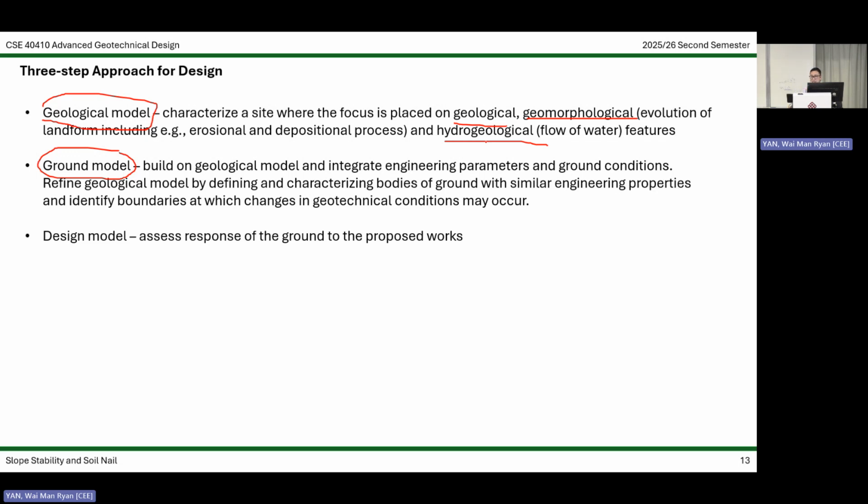In some cases, you are required to monitor the groundwater pressures over at least one wet season or at least 1 year, because that gives you sufficient information to do the design, to understand how water flows in your slope. But it doesn't mean that you can always capture the worst scenario. And you only have a few points of measurements, or I mean locations.